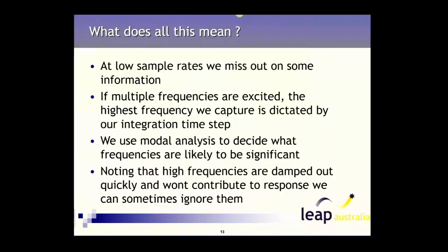So for most metals, you normally have some sort of damping. So very, very high frequencies get damped out very, very quickly. So there's no point trying to capture those frequencies by using a tiny time step, because that's going to increase your solution time, and it's not going to add any extra fidelity to your results.